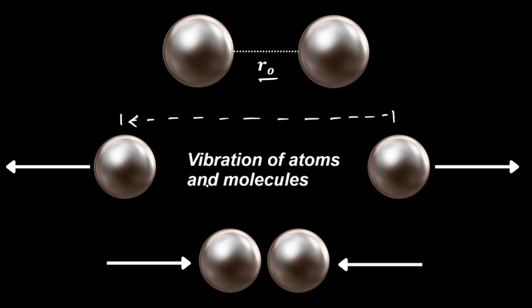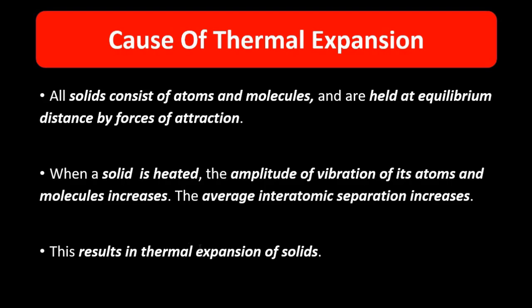So as more and more heat is supplied, always remember there is to and fro movement. When more and more heat is supplied, the vibration becomes more and more, and this causes an increase in the dimension of the object, whether it is in terms of length, breadth or height, whatever it is. There is thermal expansion of the solids. So this is strictly for solids. For liquids and gases there are different concepts. This is only for solids.